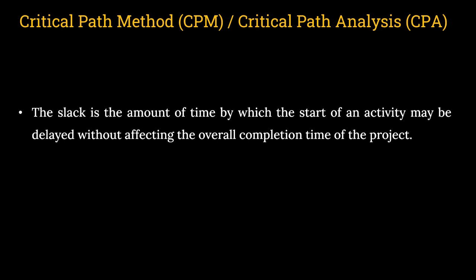Now on the critical path, no relaxation is possible. You have to start immediately, complete it immediately. If you are delayed on the critical path, your project duration will be increased unnecessarily. Other than the critical path, on the non-critical paths, there is some possibility of having some slack or relaxation without affecting the duration of the project, because that won't affect the duration of the project. Okay.